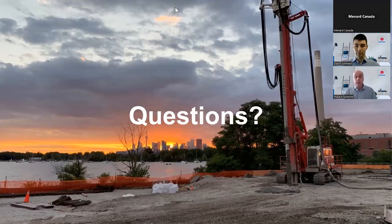For dynamic compaction, what depth can it reach? In very good conditions, so well-graded, easily compactable material, dynamic compaction can reach 10 to 12 meters in depth. If you need to go deeper than that, then we need to use the vibro, the vibro densification using a vibrating probe. And I think we own the record here in Canada, in Quebec actually. I think we've done 52 meters in depth using the vibro densification method for Hydro-Quebec.